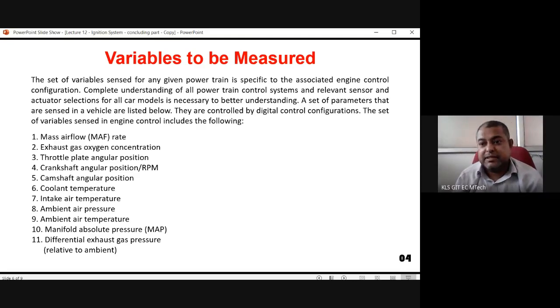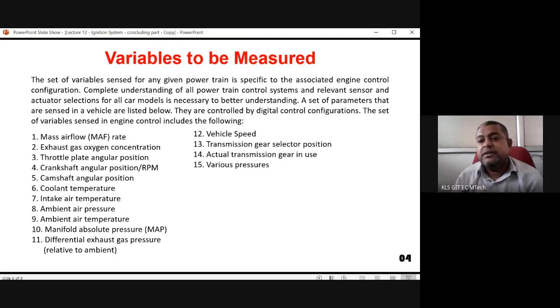Okay. And yesterday we have seen that at different angles of ignition, whether you are retarding or accelerating the ignition timing, making it very fast or very slow, depending on that, the exhaust gas components change.